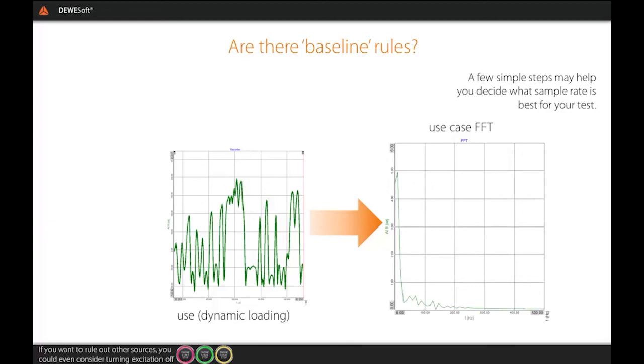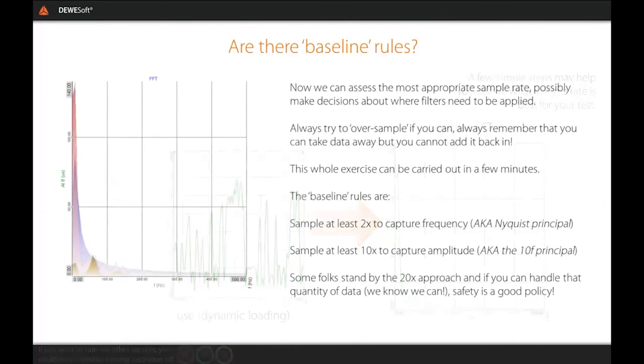And with the mechanically excited data, if it's a vehicle, for example, you might want to do some coast tests as well, by which I mean turn the engine off if it's an internal combustion engine and coast and gather data while it's coasting so that you take out the effects that are being transferred from that internal combustion engine. And then finally, we view all the results together and we look for something common. Large amplitude excursions and of course something we think unexpected.